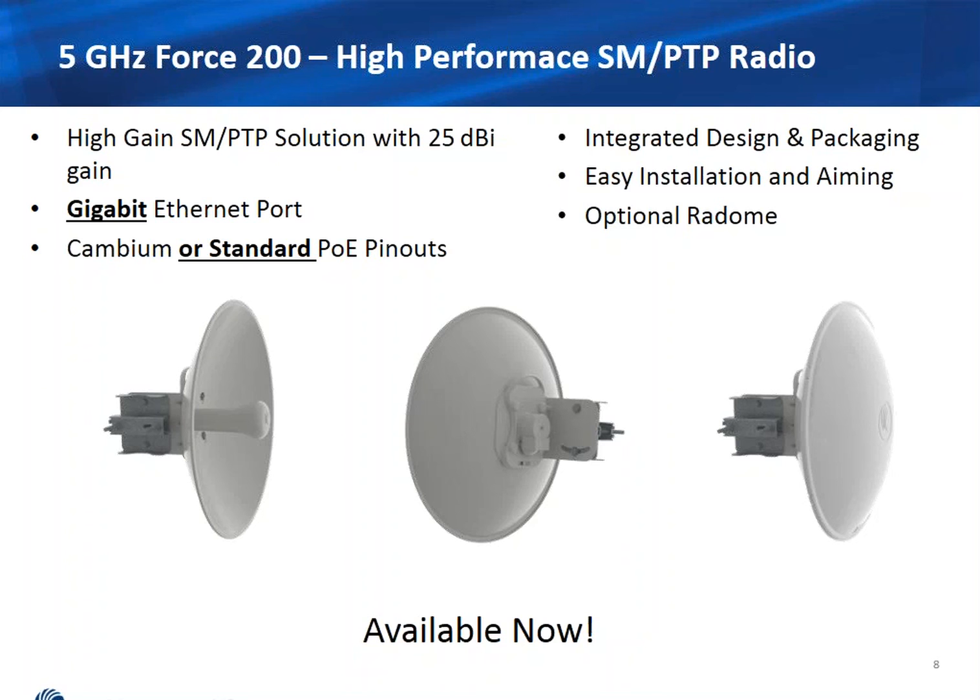The other enhancement we made is that the Ethernet port now supports both Cambium and standard PoE pinouts. Now, those of you who are familiar with Cambium products know that when we first designed the Canopy product, there was no PoE standard, and so we selected a set of pinouts that turned out to be not standard. But we've carried them through our product line all along because we wanted to maintain compatibility with previous products in the portfolio. But what we're seeing with the ePMP is that many people are upgrading their networks from other solutions that utilize standard PoE pinouts.